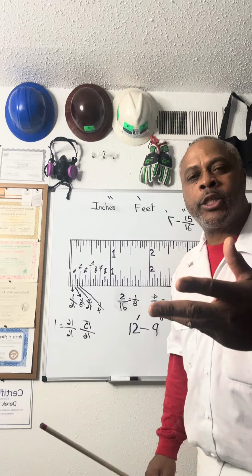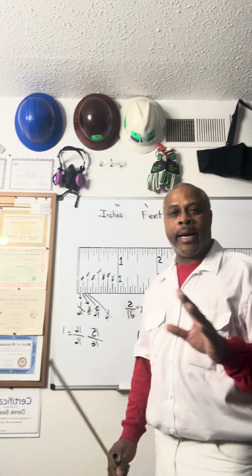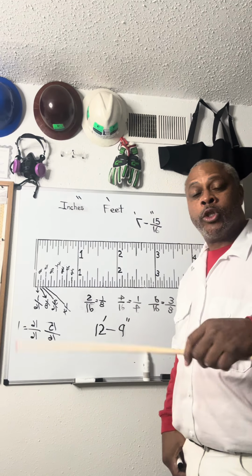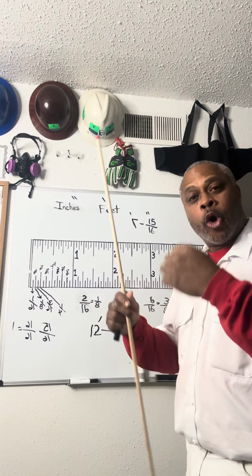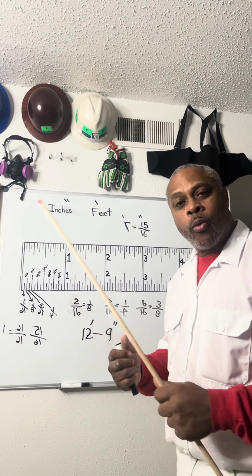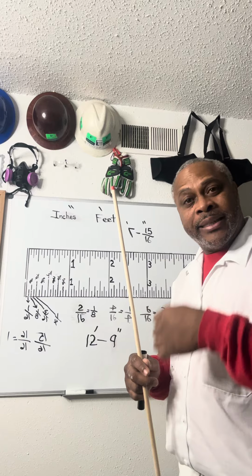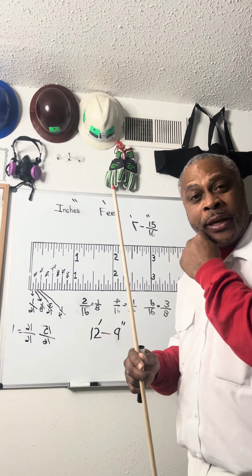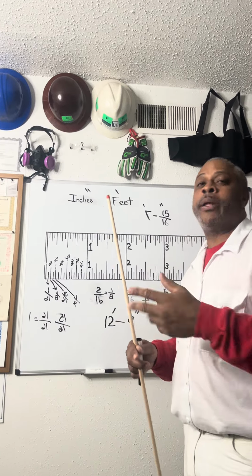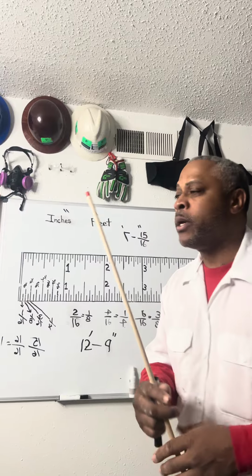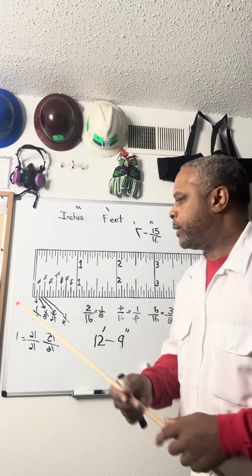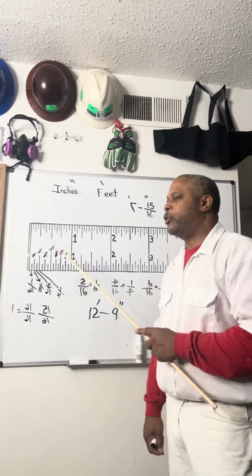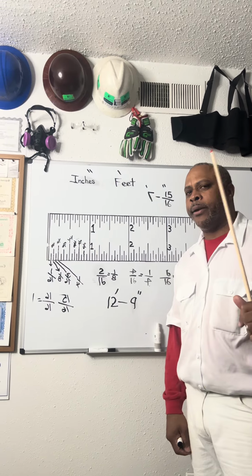And then you can have your inspection when he comes walking because you can't wrap any building nowadays without that exterior being inspected. And most of your hold downs, your Titans, which is a bolt, anchor these buildings down. You have shear walls, you have anchor bolts that are every so many feet, a foot from the corner, every 4 feet from there, or every 6 feet, depending on what the plan calls for. We'll show you that on the plans as well. So you'll be well versed in reading the measurements, okay? Because you cannot lay anything out on a building if you don't have this right here. You have to.